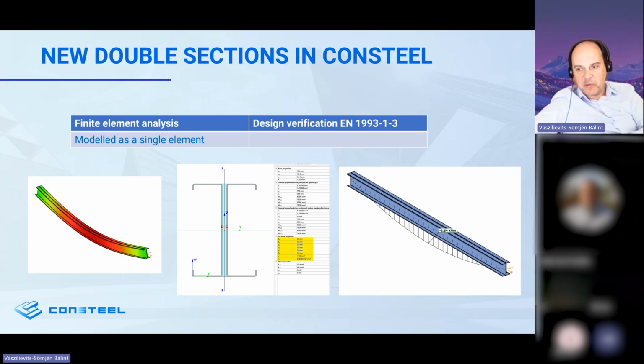Therefore, any sort of profile that is drawn, and that's the way it is also supported by the user drawn section. Anything that is drawn can be calculated, and this is now the case not only for single sections, but also for double sections. You can see here a bit strange color. This color means that the empty space between the profiles is filled with the filler material. The filler material has zero or almost zero properties, but it keeps the connection between the two elements.